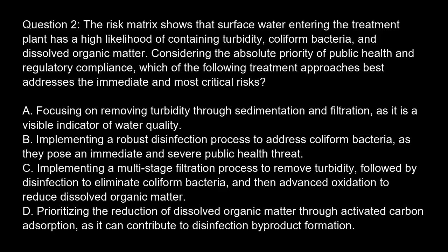Focusing on removing turbidity through sedimentation and filtration, as it is a visible indicator of water quality. Option B. Implementing a robust disinfection process to address coliform bacteria, as they pose an immediate and severe public health threat. Option C. Implementing a multi-stage filtration process to remove turbidity, followed by disinfection to eliminate coliform bacteria, and then advanced oxidation to reduce dissolved organic matter. Option D. Prioritizing the reduction of dissolved organic matter through activated carbon adsorption, as it can contribute to disinfection byproduct formation.